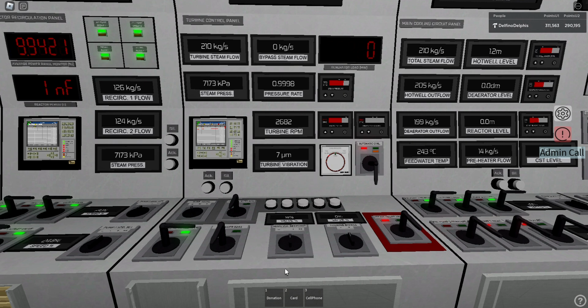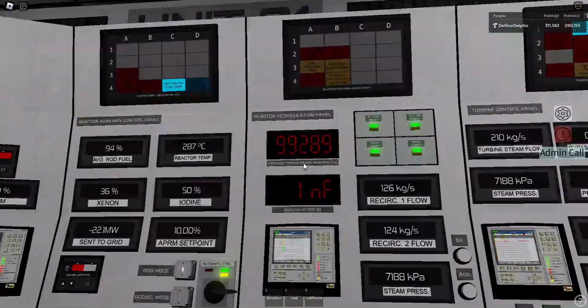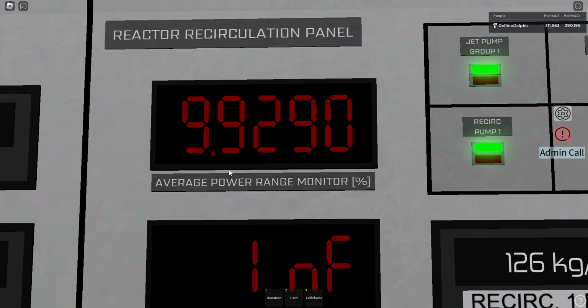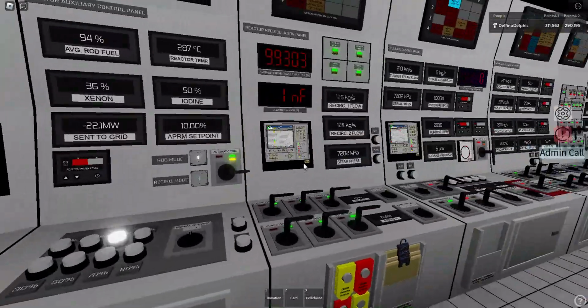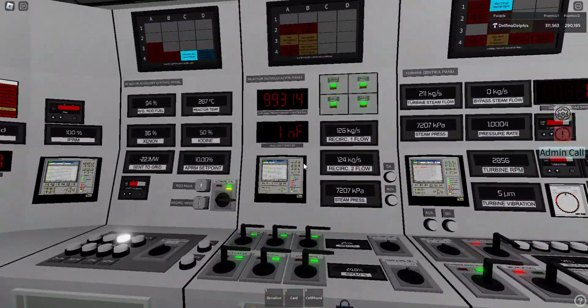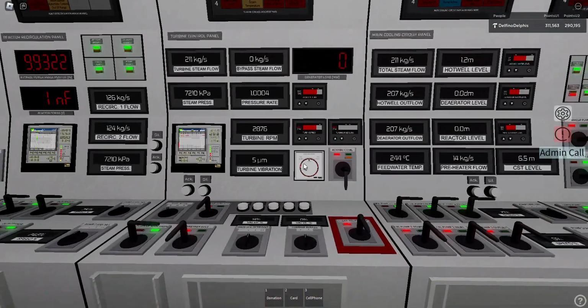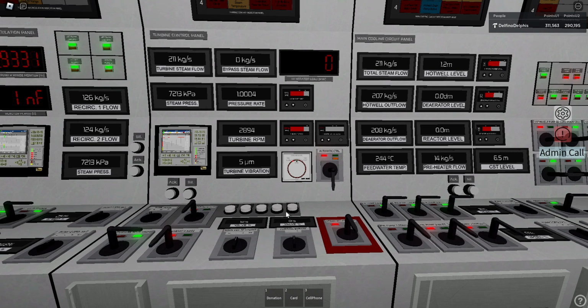If you want to close the turbine valve and not raise the pressure, you might want to use the bypass a little bit. But generally, if you do it at 10% of reactor power, this should be almost ideally set up for you. If you are more experienced, you can do it at 15% or even 20%, but then you will have to rely a lot on the bypass to synchronize it. So our goal is to reach 3600 RPM, and then we want to stop there.